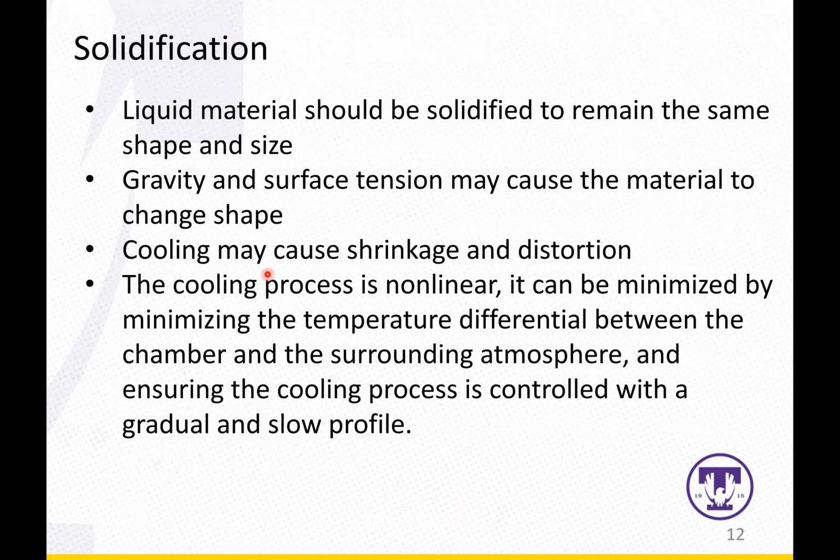Also, the cooling process is nonlinear. It can be minimized by minimizing the temperature differences between the chamber and the surrounding atmosphere, and ensuring the cooling process is controlled with a gradual and slow profile. Because although there is some fan on the printing nozzle, there's still no other cooling channel or something like that to actually cool the extruded material.